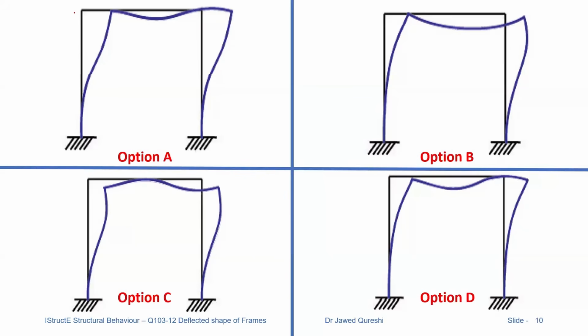First, let us assess option A. So when we apply loading at the top, this will create deflection in beam. And here 90-degree angle is maintained, which is fine. And here we have theta 0, which is fine as well. Here we have tension and tension outwards, tension and tension at the top. Here we have tension, and on this side we have tension. On top of the beam we have tension as well. Now this satisfies all the requirements.